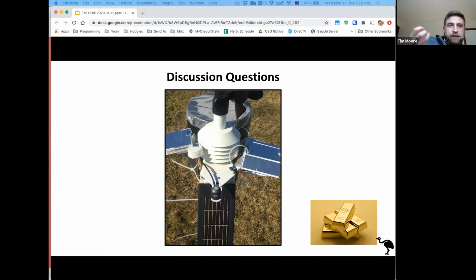In a similar way, if you had no shielding for your sensor unit, you run the risk of the actual sensor itself heating up, and the different properties of the sensor unit itself may heat up at different rates. Depending on the angle at which you place it in the environment, and how much direct sun it's going to receive, all these things could affect the temperature measurements that you get.